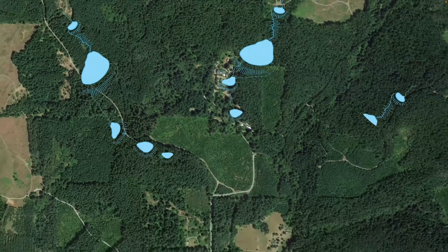So in this way, if we're actually diverting water out of a drainage, we can be sure that the bulk of the water during the rainy season continues through the spillway and through its natural riparian ecosystem. But the surplus water, or a portion of that surplus, can flow to the trickle tube and be carried out and beyond the valley. It can be carried out to the ridge, or it could even be allocated to go to a valley pond the next ridge over.